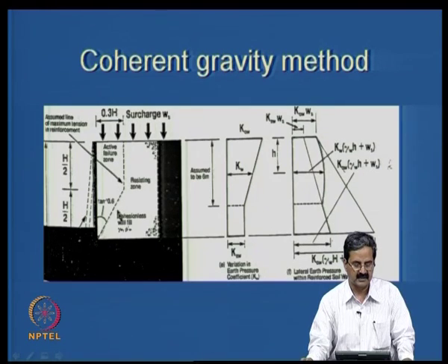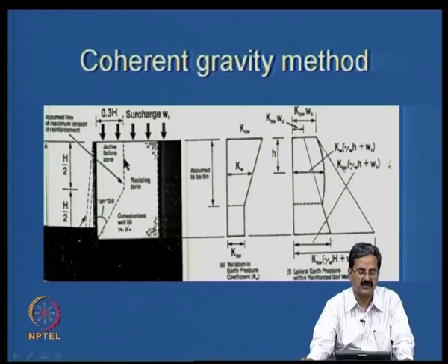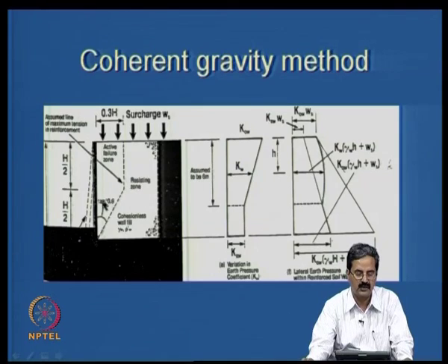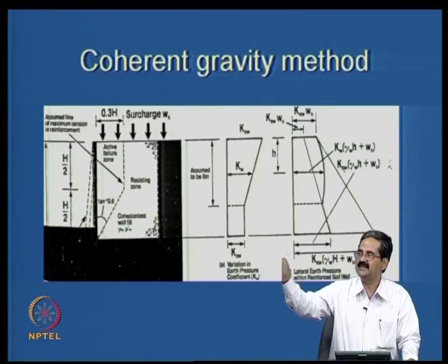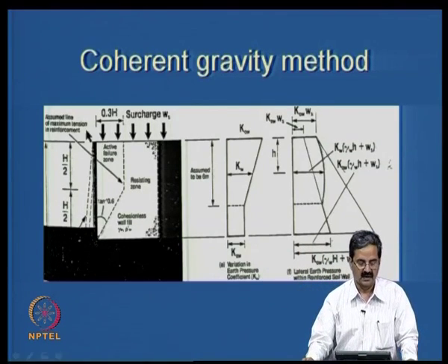What people have done is use finite element analysis, or experiments also. People have measured using centrifuge. You can put reinforcement and measure its tensile strains. So the point at which it is maximum, we have seen even in the Binquet and Lee method, they assume some maximum strain distribution, and we made some assumptions there.